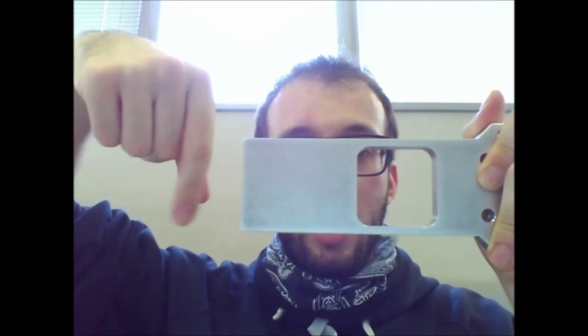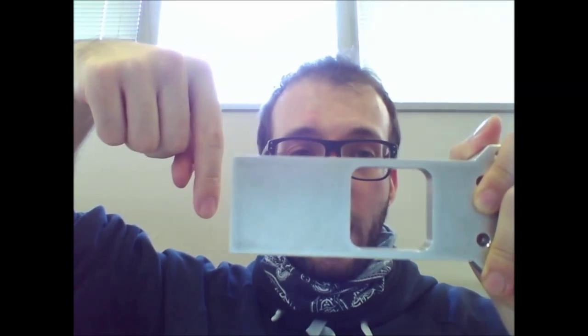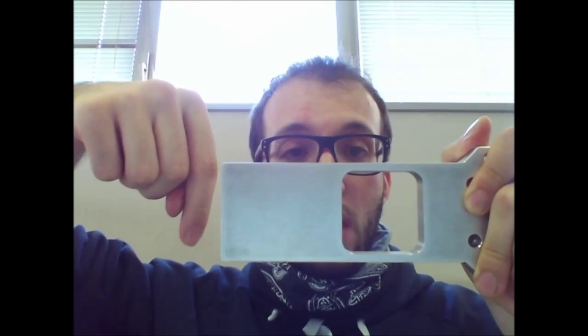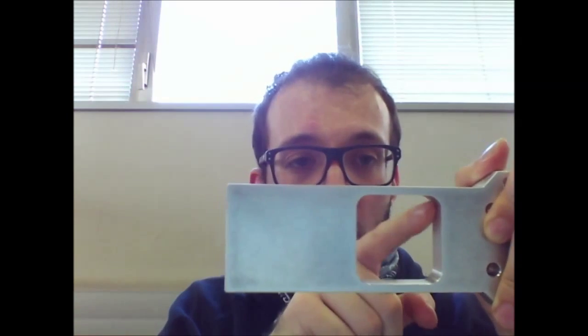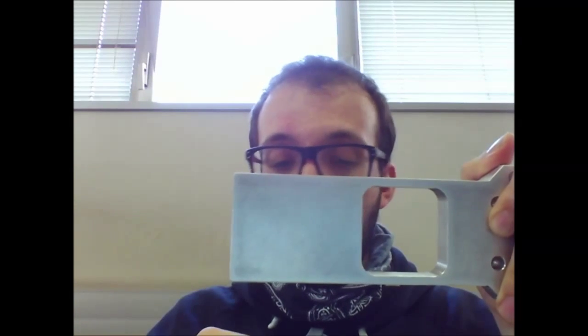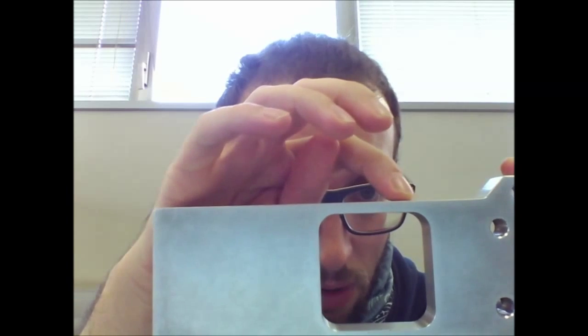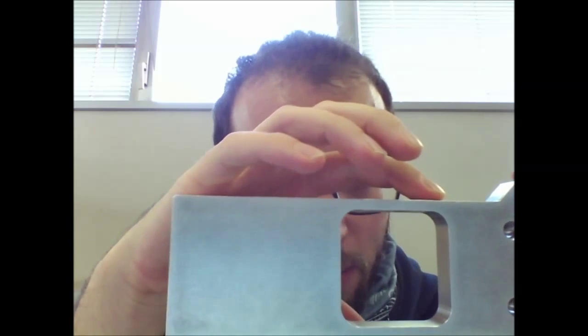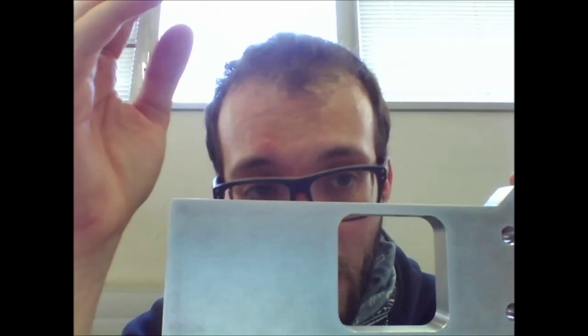Any kind of load applied to these systems generates stress, and with particular shapes using holes and other artifacts, you can get stress concentration in some area. For this load cell, this area is subjected to stress concentration, and as a consequence, here is developed a sensible level of strain.